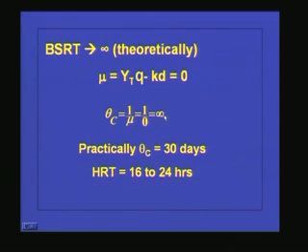But practically, we cannot provide infinite time in the aeration tank. So usually we give a theta c value of 30 days and a hydraulic retention time of 16 to 24 hours. So that is the extended aeration system.